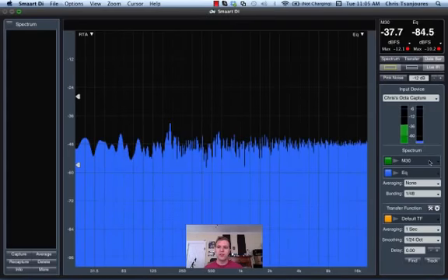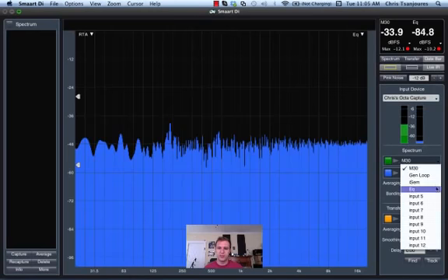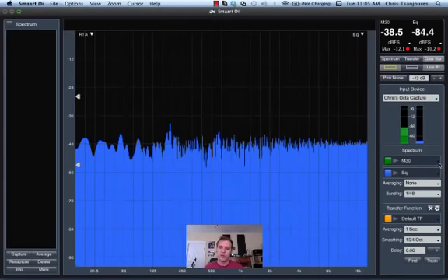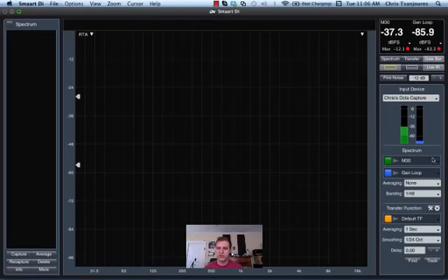Okay, so now I've got all these different channels set up, and I'm going to be switching back between them. But what I want to do is have many configured pairs for when I'm doing the transfer function measurements. So this first pair that I'll be using will be the M30 against the generator. So I'm going to name that my M30 or mic 1 pair.